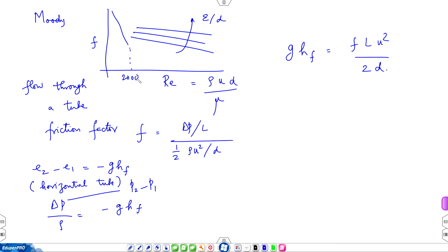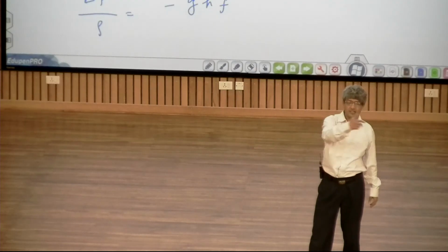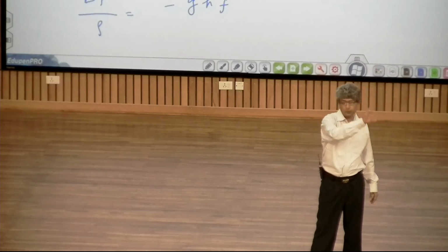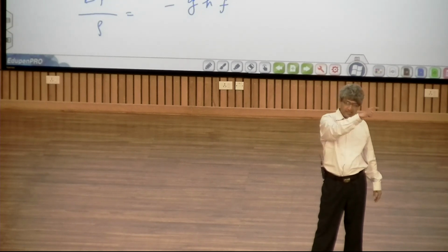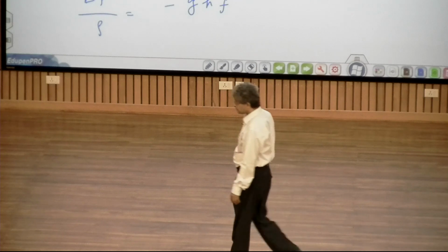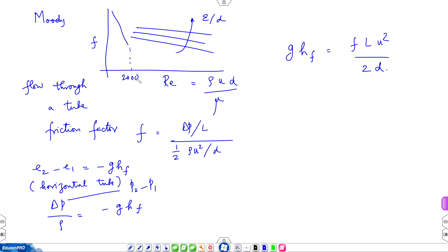Okay. So, the lower limit is for 0 roughness, otherwise you have to pick the roughness and read the friction factor out of it and then put it in the formula f L u square over 2D and find g H, and when you substitute there is a negative sign over there in the energy equation.